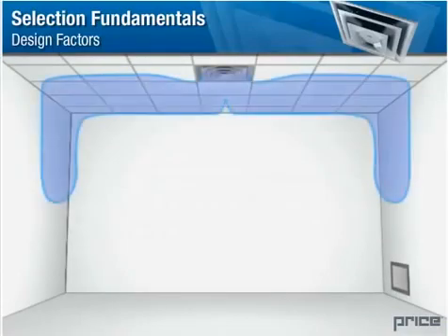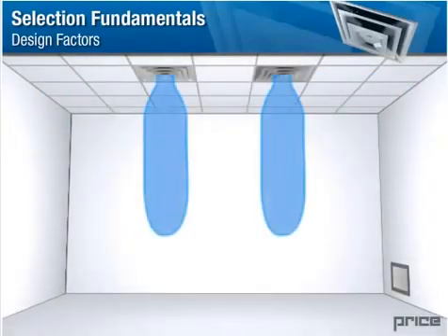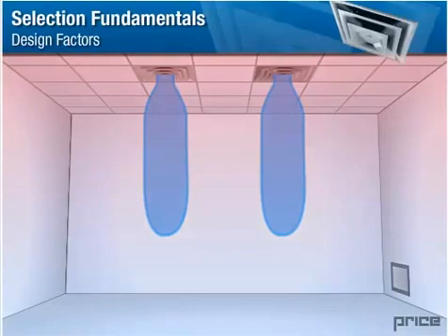If we supply all the air through a single inlet, this may result in uncomfortable drafts in the occupied zone. If too many outlets are used and the supply air volume per outlet is too low, the system will not properly mix the air in the room, and the air may become stagnant or stratification will form. Either way, the occupied zone will be uncomfortable.